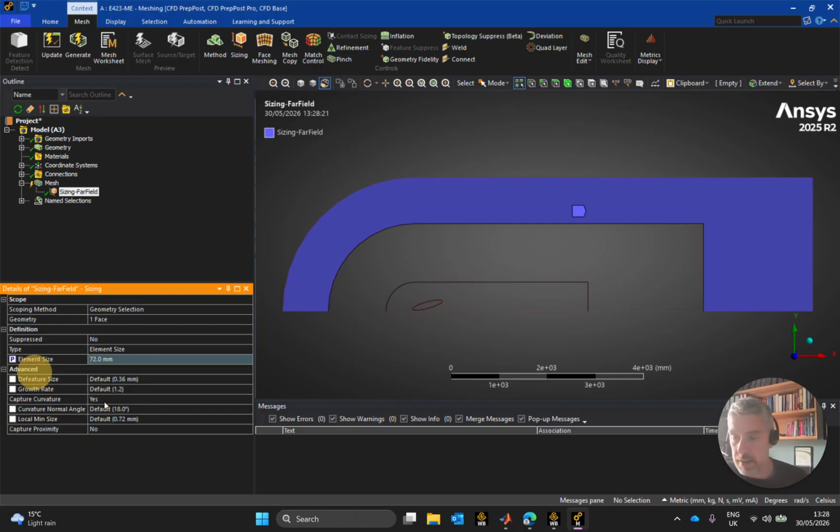I'm going to make that a parameter because when I do my grid convergence index study, I'll want to refine these down, even though with a 72, knowing that I'm going to be refining these down by a factor of 3 or 4 from stage to stage as I approach the airfoil, I'm going to be dealing with a very resolved mesh, a very fine mesh at the outset.